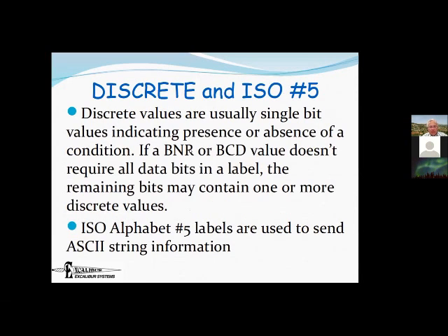Okay, discrete is on-off, landing gear up, landing gear down, that kind of thing. And if it's landing gear up or down, it might be landing gear talking to the flight computer. And one thing that we see on 429 devices, they very often have quite a few 429 ports, some input, some output.